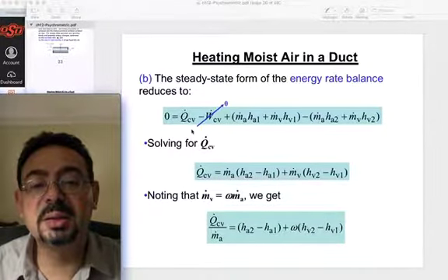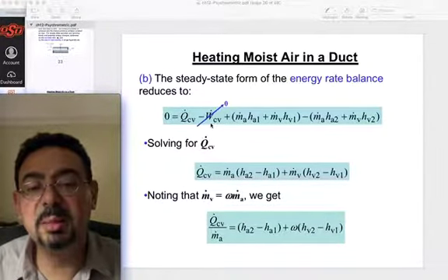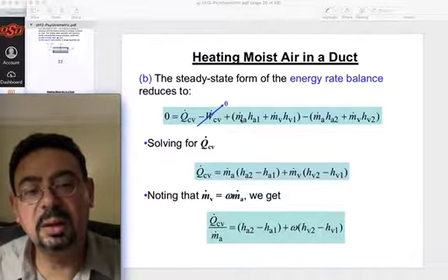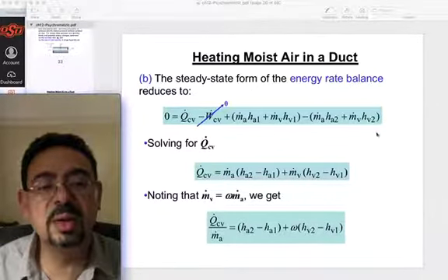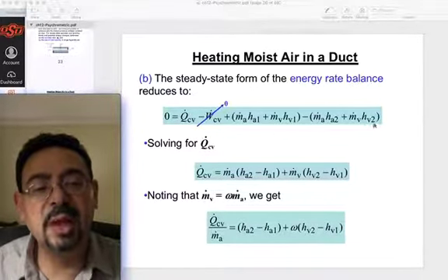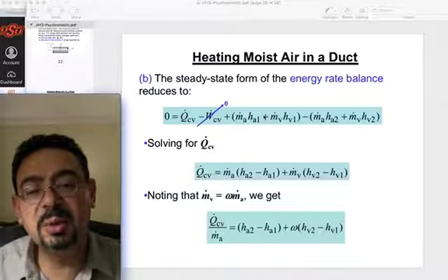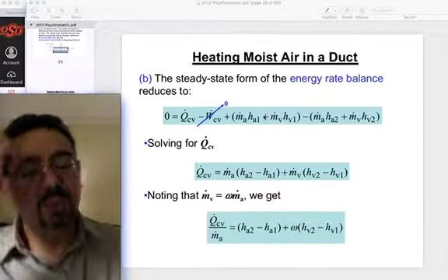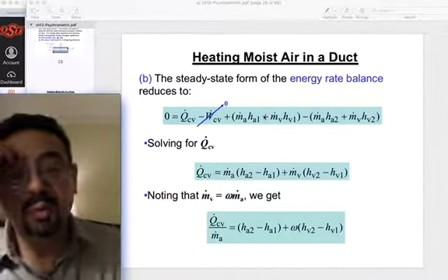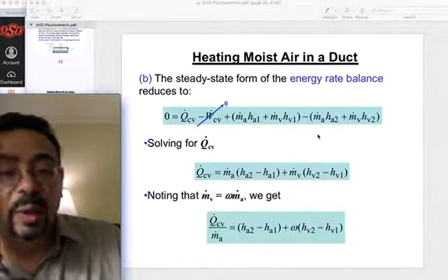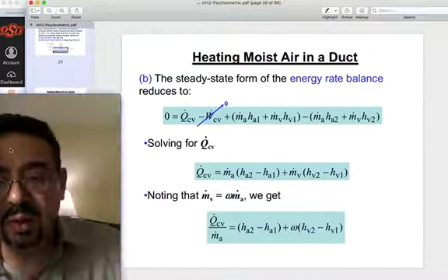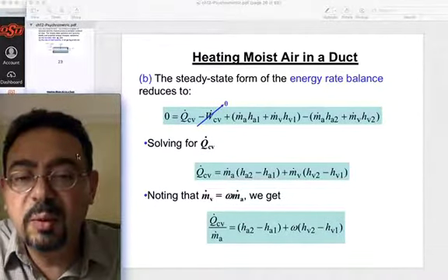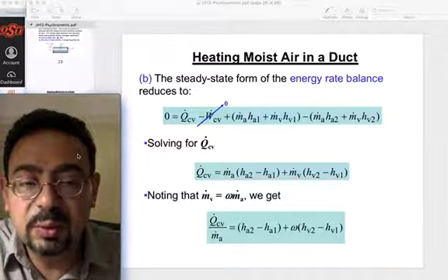So here it is, q minus w equal, and again I memorize it, you put it on the other side. On the other side it is m dot out h out minus m dot in h in. I think it would be nicer if you just remember it always in that form. But anyway, this is exactly the same. So in case you want to just bring this formula from the book, that is fine with me too.